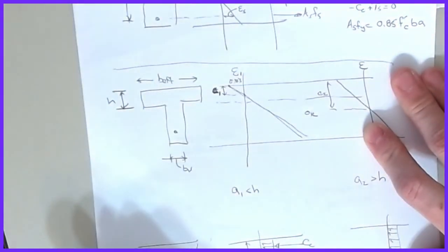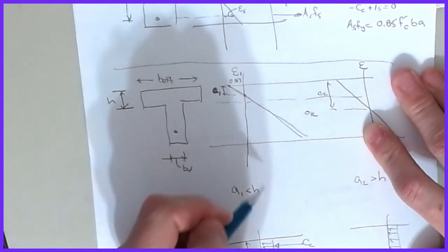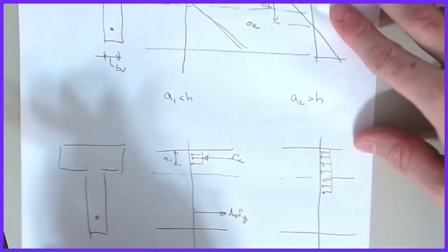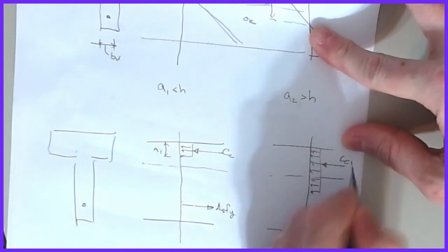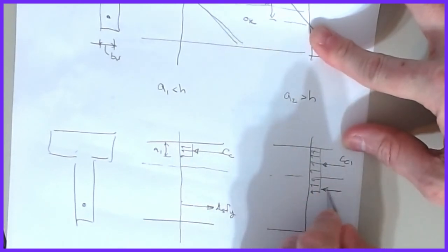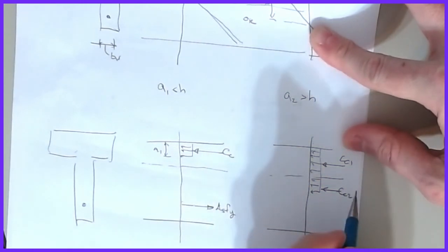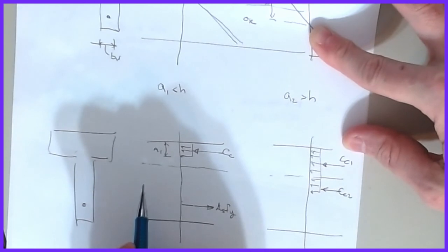Right? So for where the neutral axis is located, you're checking if the neutral axis is in the slab versus. I had it right here, I wrote it down wrong there. So what happens here is now you end up with a Cc1 there, but you pick up a Cc2 here, right? And they were different values because the width was changing on all of these.